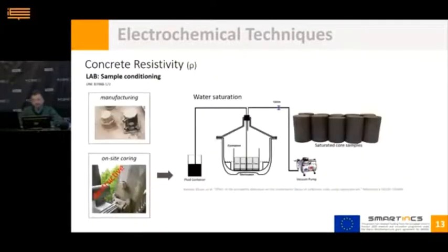This is the case of laboratory studies, where the usual objective is to evaluate the durability performance of a specific type of concrete, and these are standardized tests, okay? And the aim is to eliminate all variables other than concrete porosity. Therefore, cylindrical specimens manufactured with specific geometry are used, or cores extracted directly from existing structures, the latter being a destructive test, okay?